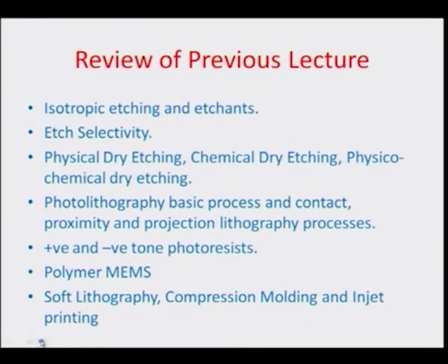We talked about various etchants and isotropic or homogeneous etching technique. We mentioned etch selectivity and selective layers. We also briefly talked about physical dry etching, chemical dry etching, physicochemical dry etching, where use of plasmas would enhance the directionality or anisotropicity of the etching process.